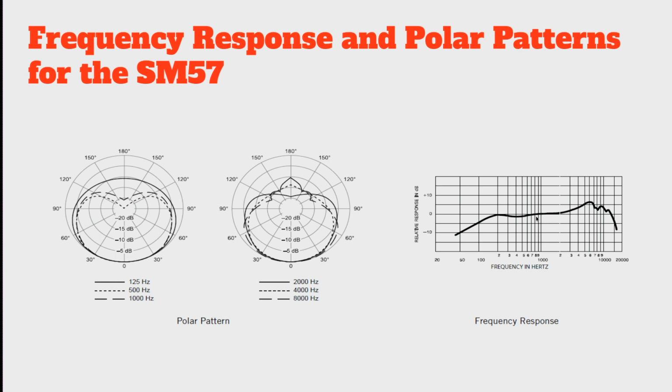We stay relatively flat going down until we get to about 400 or 500 hertz and we get this little dip. Then as we move into the low frequency range, we can see this rolls off quite a bit, in fact, quite precipitously. By that 40 hertz frequency they gave us for the bottom end of the frequency range, we can see that we're actually down by a little over 10 dB. If I recall correctly, it's about 12 dB down at 40 hertz. So it's definitely a significant drop-off in the responsiveness at 40 hertz.